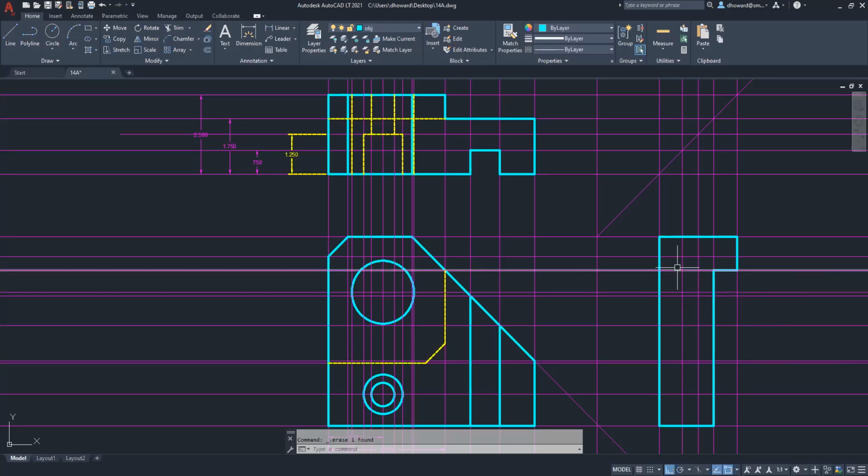So again, this line comes across from the intersection of this angled face here, where this vertical line meets that horizontal line right there. And then the other thing I need to cut out on this face is where this slot is right here. Pretty straightforward. Just go from there to there. And then trim that out.